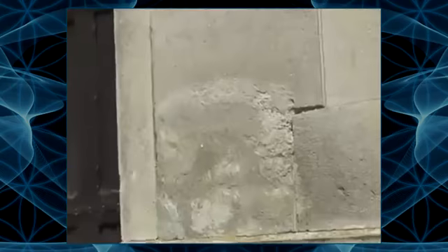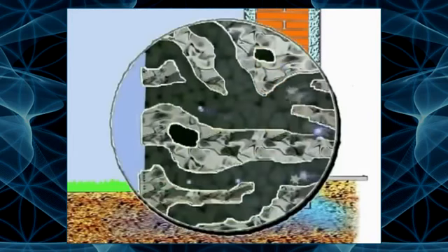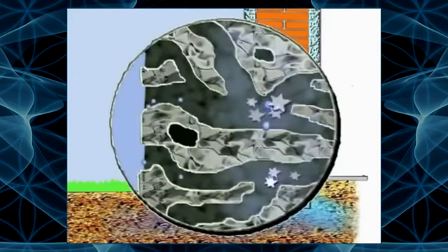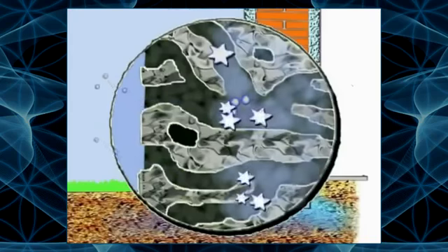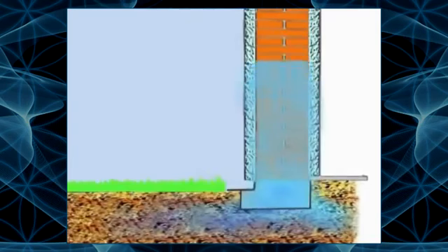In conventional plasters, salts usually rise to a visible plaster surface when they crystallize. The pressure of such crystallization and other chemical and physical mechanisms eventually destroy the plaster. In so-called renovation plasters, the aggressive salts are deposited in the lowest layer of plaster. The salts clog these pores and the plaster becomes waterproof.